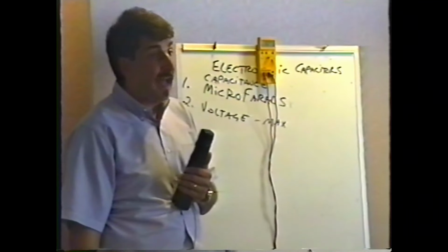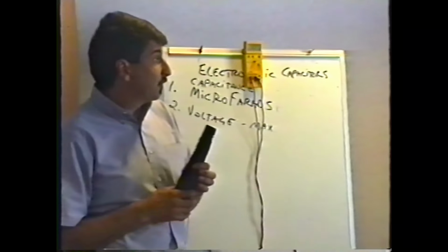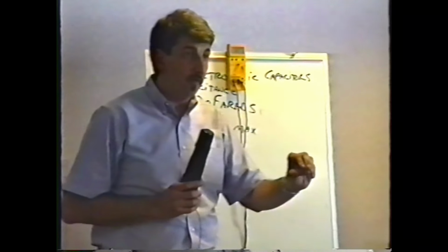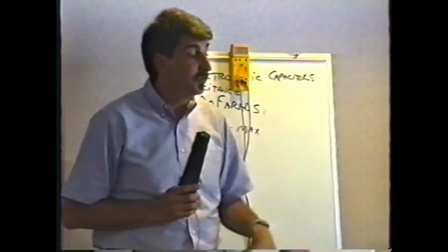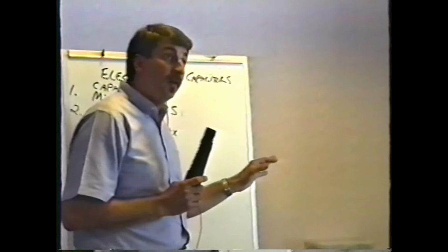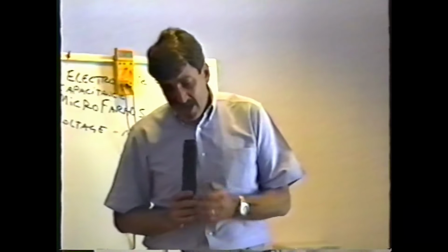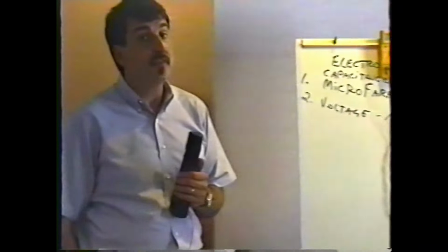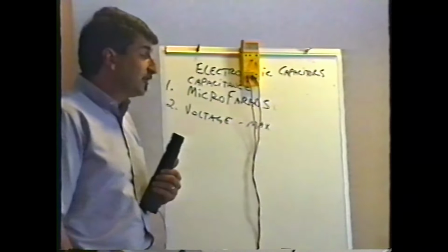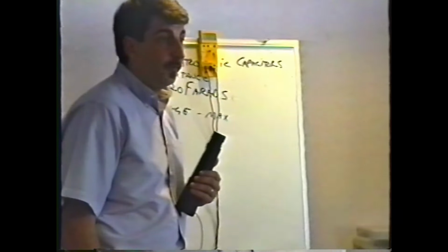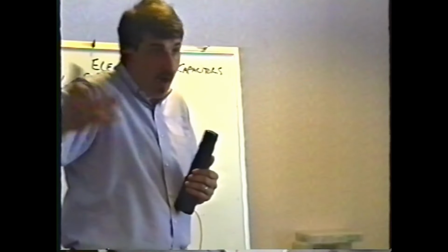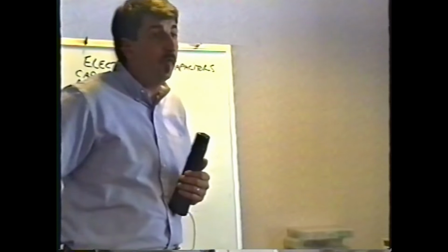It's a hassle. For $80 or whatever it's going to cost you for a capacitor meter, if you're doing a lot of monitor repair, especially because that's where we have a lot of cap failures, it's not a bad idea to have a capacitor meter. Quite frankly, though, when I have bad capacitors in a monitor, and again, we're going to discuss this in great detail on Thursday, I usually end up changing just about all of them anyway, on the theory that when one's going bad, they're all probably going bad because they're all the same age. We might as well get rid of them all.